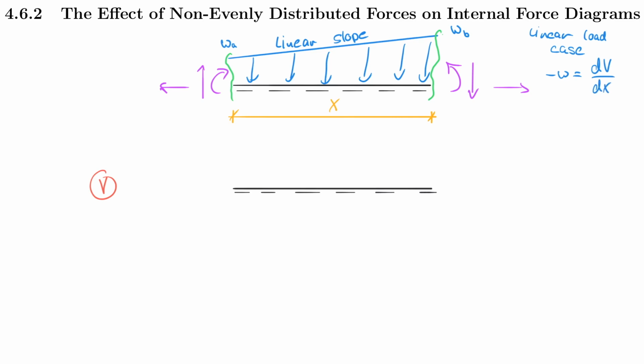And thanks to that formula, I can now extrapolate my knowledge from the previous section and understand that I can also take the load case and integrate to arrive at the shear force function. So now it becomes a little bit tricky because we have the minus here, but there's nothing that we cannot solve. We can, however, use the similar logic and move from this sloped line to the shear force function here.